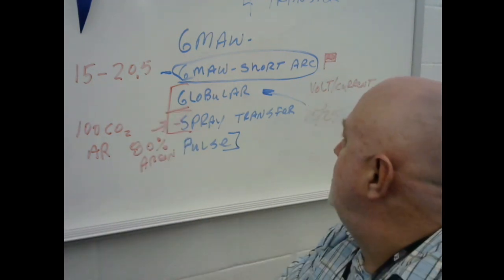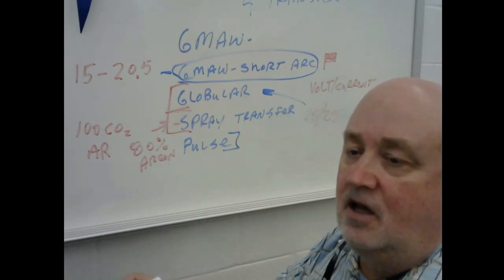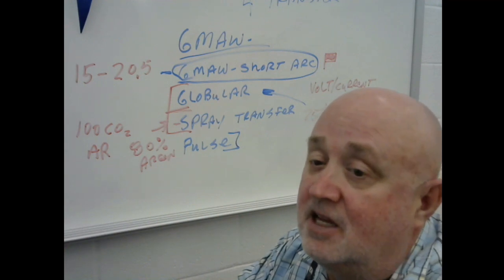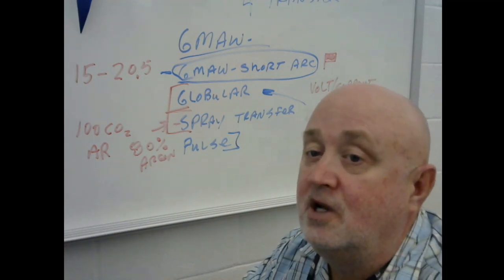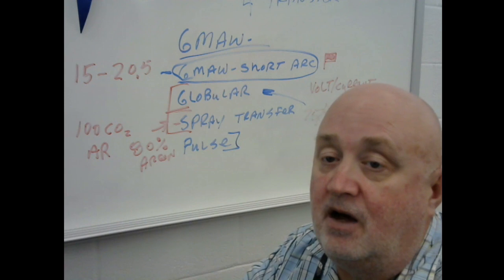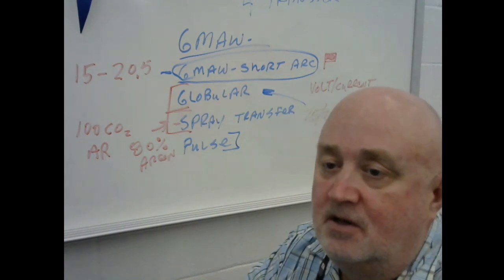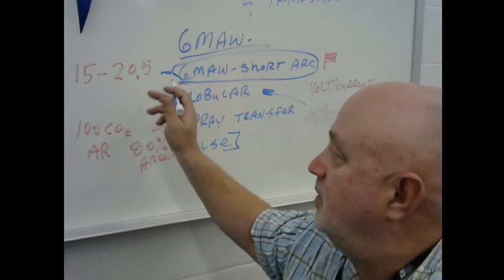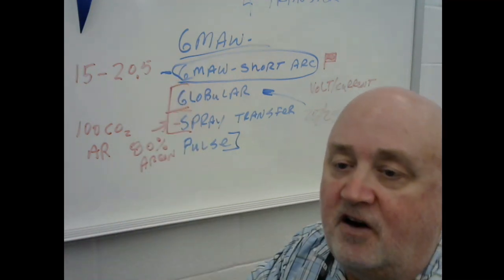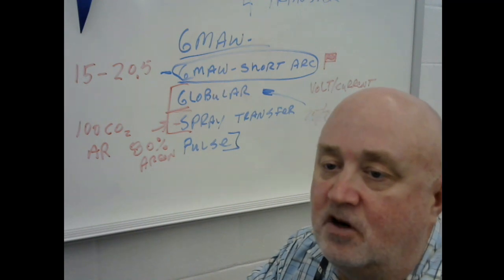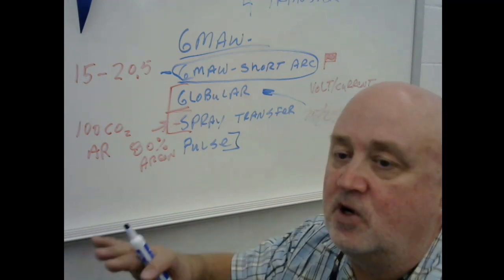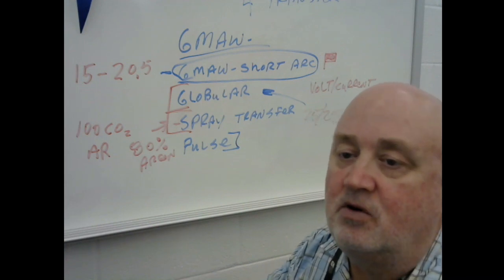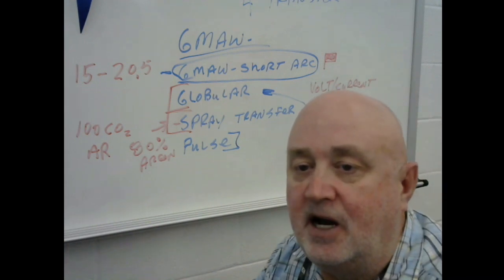But you start getting into this and dealing with welders. A lot of times if they think you're the engineer and you don't have a clue, they might say, oh well, I'll just do this weld. I've got to do this weld. It's out of position. I'm just going to run it in there with GMAW short arc. We'll turn the wire feed speed and the voltage and the amperage way down, and then I'll run this out of position. We don't have to flip it. Nobody's going to know. Well, no, it doesn't work like that. So sometimes you've got to keep an eye on these things.